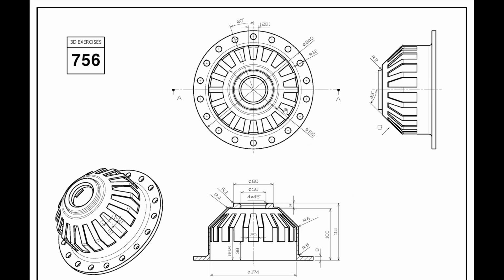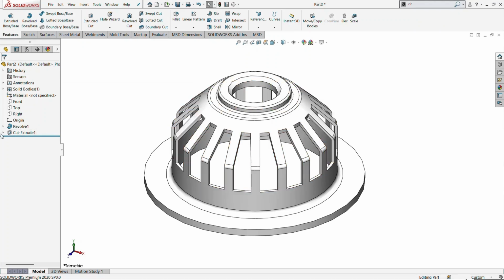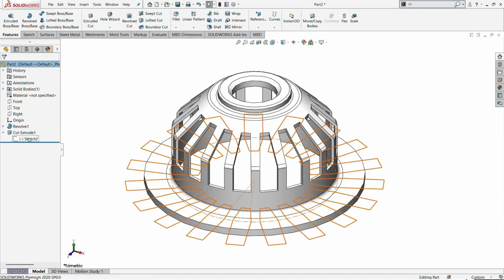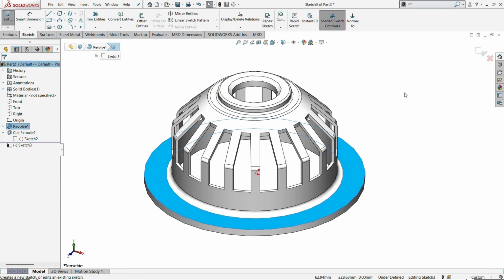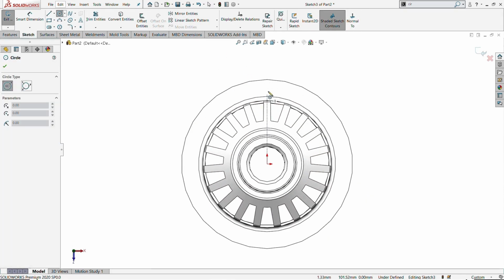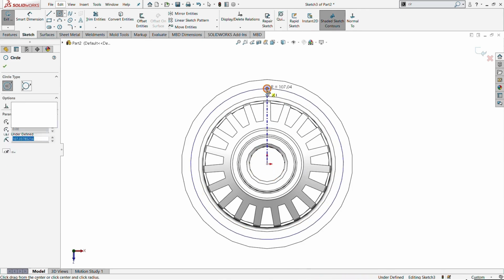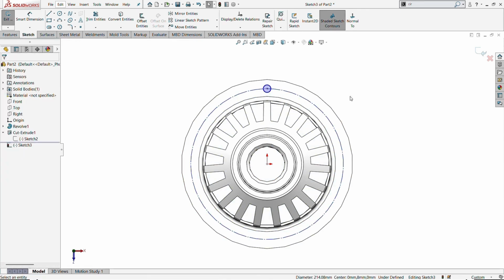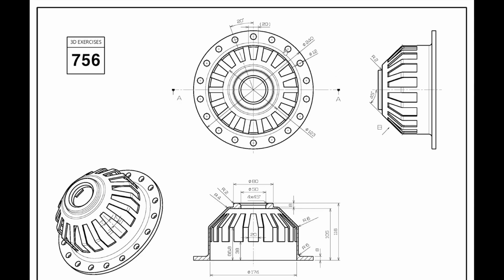The only thing we need to do from this portion is the circular pocket. Look at the diameter of that, 12 mm diameter, and instances of different types are also created. Now selecting the top face, create a new sketch and draw one simple circular profile at the top quadrant point. Also draw another pitch circle from the center point. Transfer that into a construction line because it is only for reference purposes.